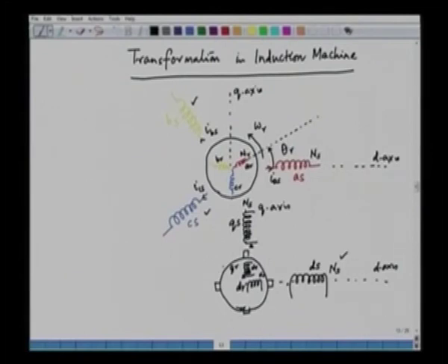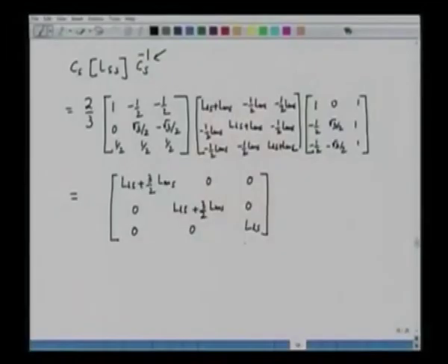The D and Q axes are orthogonal to each other and perfectly decoupled, hence the off diagonal elements become 0. In addition to the DQ inductance, we also have the zero sequence inductance. The zero sequence winding does not have any coupling with the D and Q axes. It can be assumed to be a winding in the Z direction, or in a plane perpendicular to the plane of the slide. So, we can think of this as the zero sequence inductance.